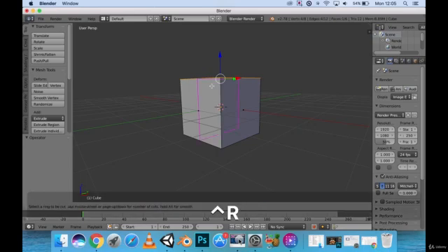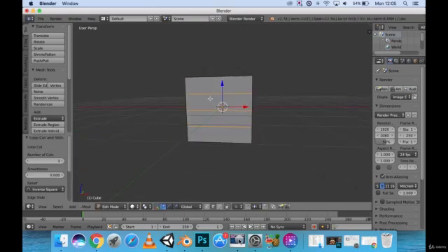I'm going to click Control R, and if you want multiple faces cut, like 4 faces making quarters each, you can simply scroll our mouse wheel and just scroll up. As you can see, we've created these outlines for our edge loops. It created 3 edge loops, and it's going to be cutting it so that there's 4 faces in the center face right here. We can also put it up on the vertical side here. I'm going to place it here, double click, and there you go. We have perfect cut sizes here.